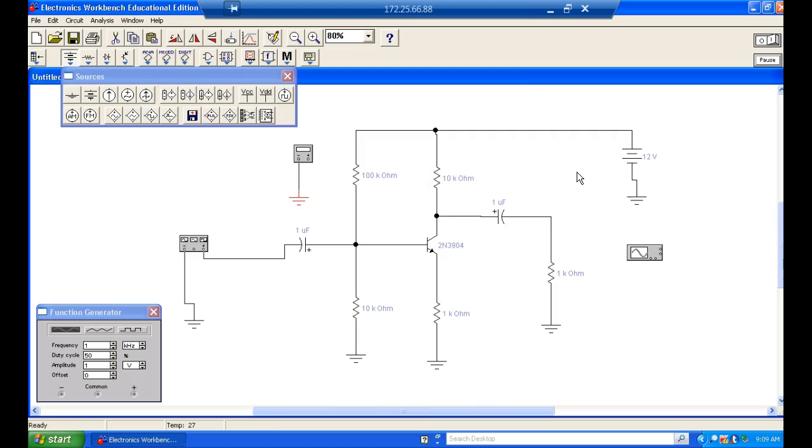So what do we want to try there? Well, let's do it. Hit and miss. 50K would probably be way too much. Maybe 25. So let's say what voltage do we want right here? If we want this at 6, then we want this guy right here to drop 6 volts. What current would I need to drop 6 volts on a 10K resistor?